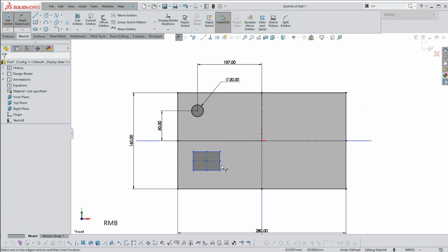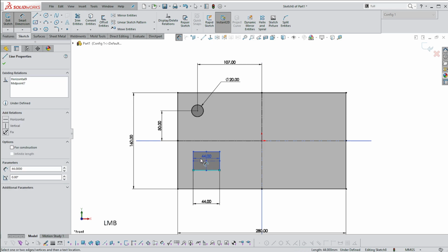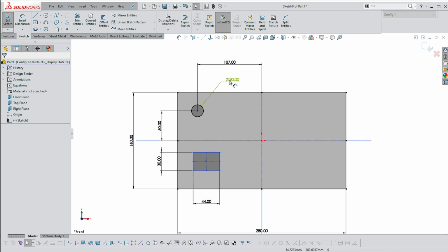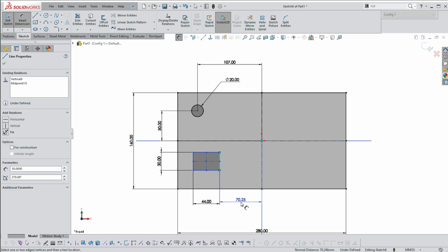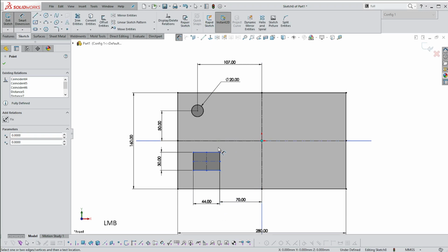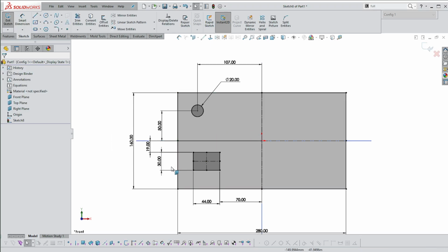So what happens if we have an item which has more than one size position? Okay, so this has two sizes. I think that should be obvious, 30 by 44, whereas that only has one. It's a diameter, a circle of 20. So what I can do is go from the datum to one side, and then from the datum to another side, or I could go to that side, whichever one's more important to me. And now it's fully defined.